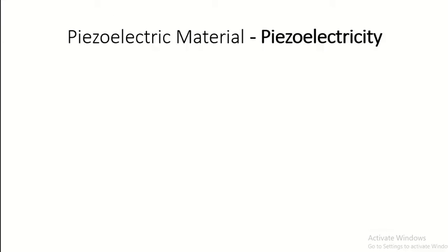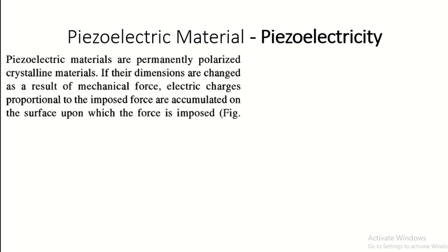So coming to the first property, piezoelectricity. Piezoelectric materials are permanently polarized crystalline materials. If their dimensions are changed as a result of mechanical force, electrical charges proportional to the imposed force are accumulated on the surface upon which the force is imposed.